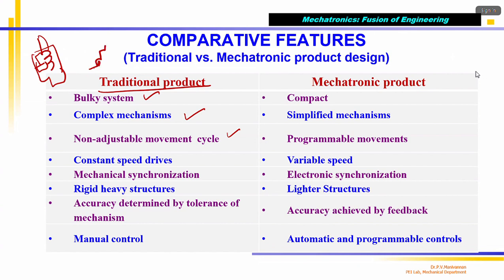You can adjust the pre-tension, the spring tension. I call the stiffness, KS, can be adjusted. There will be a small lever like this. I can push it to different notches, so that the stiffness of the spring can be changed. If you see a motorcycle shock absorber, you'll see this. By loosening this nut and moving it to the next nut, tighten.